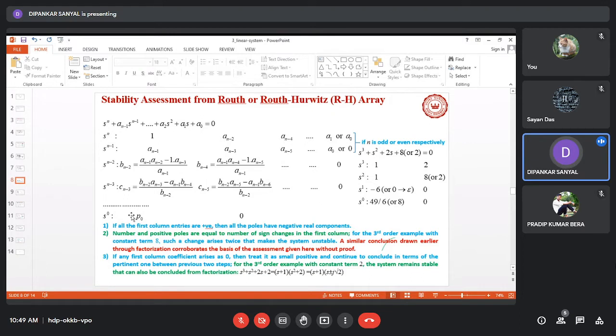Fifth line will be constructed on the basis of third and fourth line, and in this way we proceed till the end. I mean, if we consider the largest polynomial of the first line, that is s to the power of n, so in the second line, the largest polynomial will correspond to this s^(n-1). So if we go by reducing the order of polynomial by 1, the last entry will be a constant, and in this way we will keep on generating the coefficients till the last one.